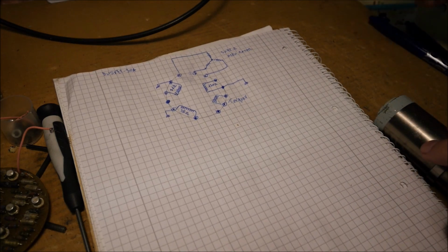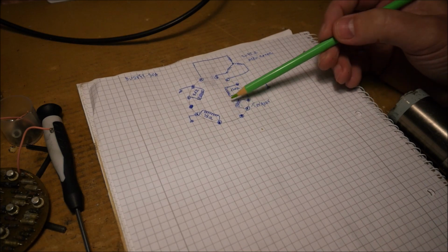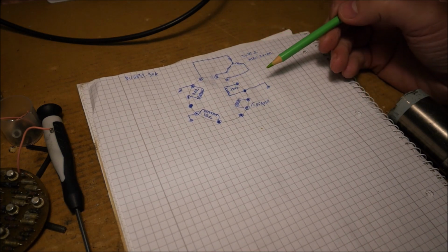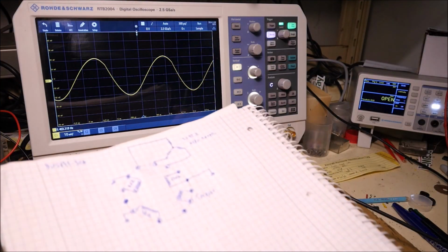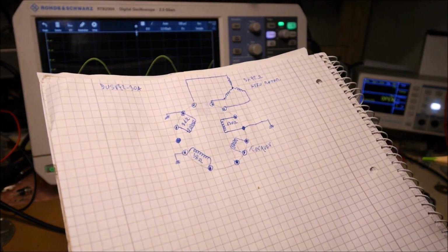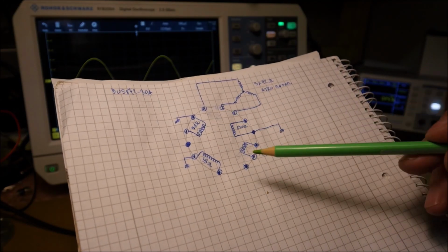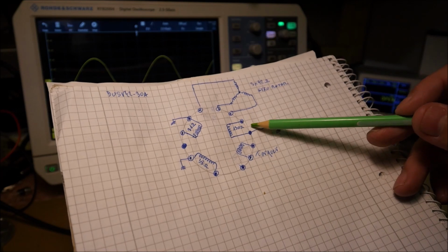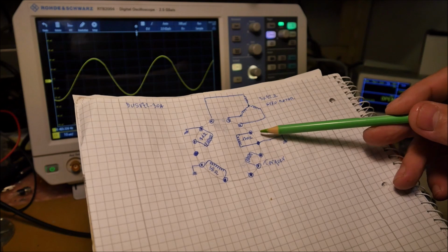So we should have the zero detector, the pick-off. It can be any of these coils here. So I will apply an AC voltage between these two terminals. So I have found the pick-off. One winding is this one, second one this one. So I have applied here an AC voltage, 400 Hz, 2 or 3 volts RMS or something like that.